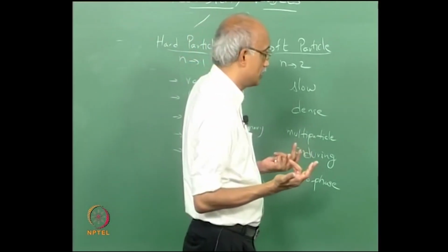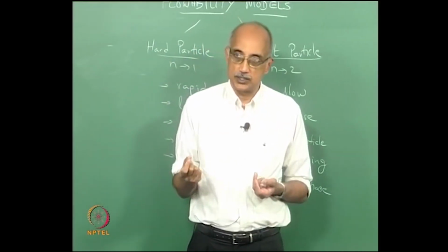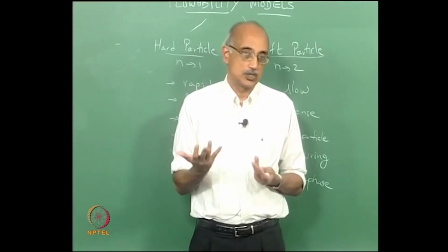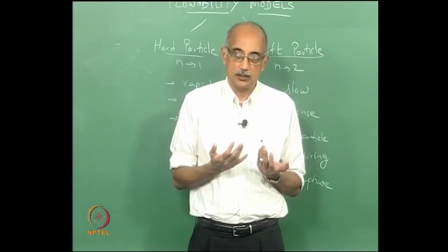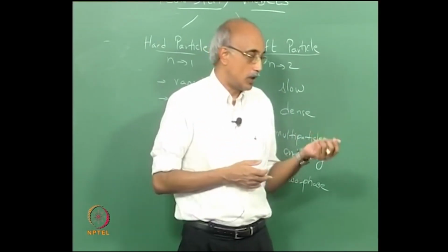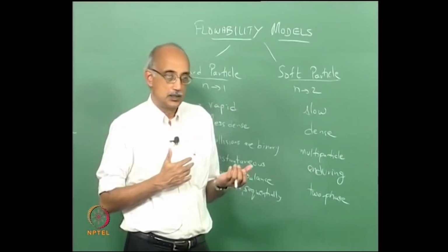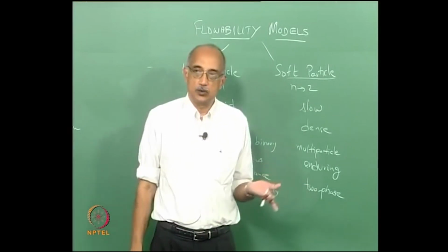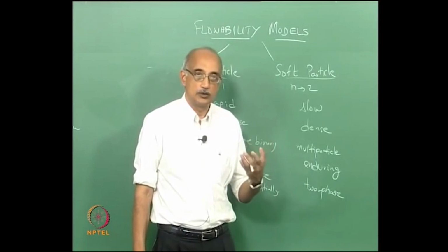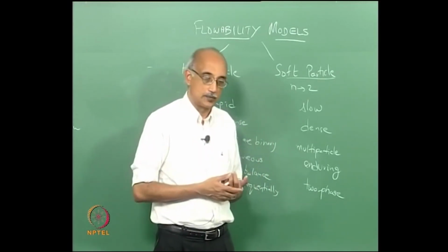You can try to be very, very precise, and that adds to the cost and complexity of the testing, or you can do reasonably crude testing, which you can do at low cost, but then the data that you get is of questionable value. Whereas modeling in this particular case is fairly well established, and there are commercial CFD codes that are available which can actually predict how granular material will flow under various conditions of charging and discharging and so on.